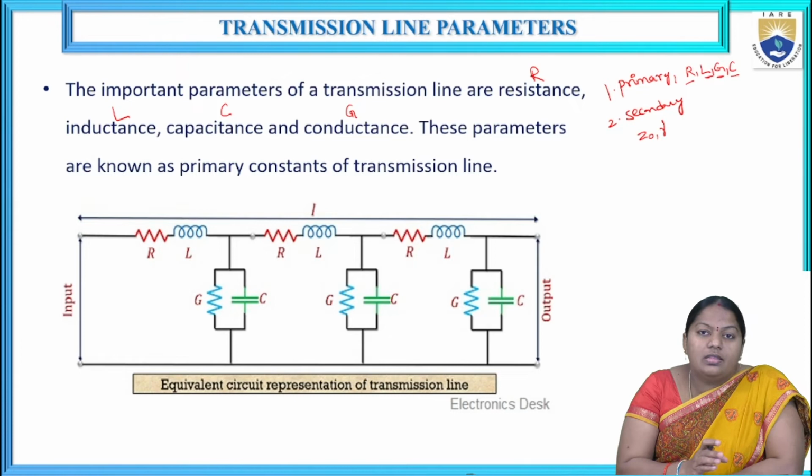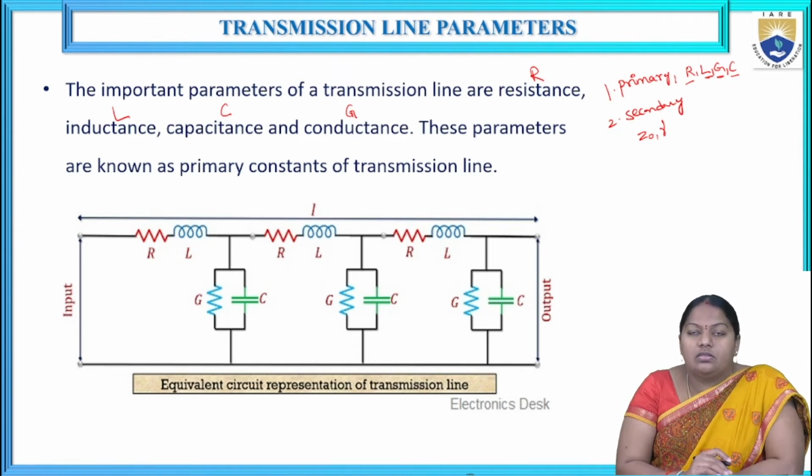Basically, if you consider the length along a transmission line, one of the parallel wire type or open wire type, suppose the length is up to 1 kilometer. Throughout that length of 1 kilometer, it is divided into subsections with lumped elements. A lumped network consists of only 4 primary constants. If you combine all lumped elements throughout that 1 kilometer length, then such networks are called distributed networks, meaning all the lumped elements are distributed throughout the length of the transmission line.